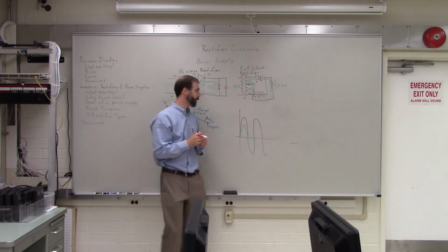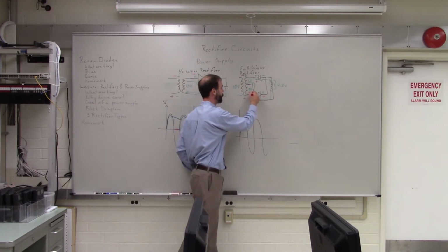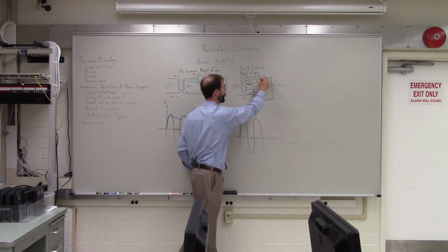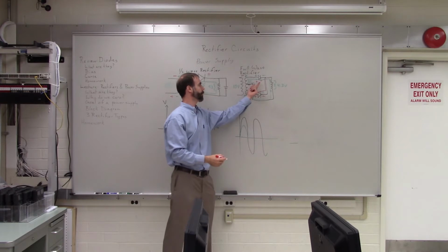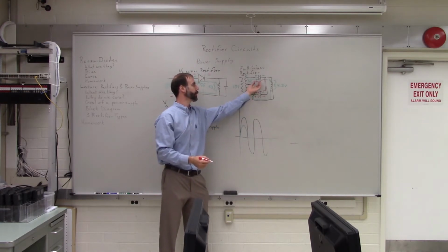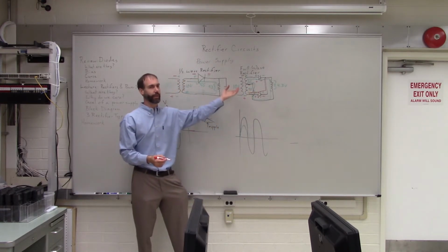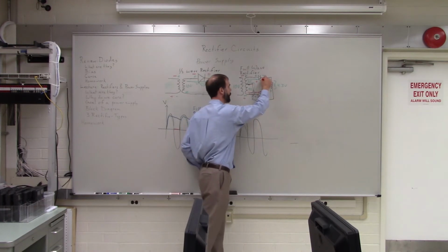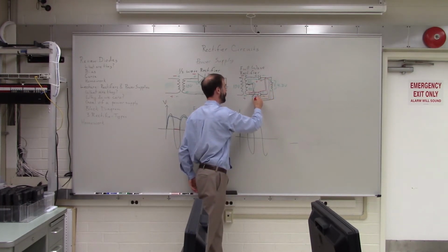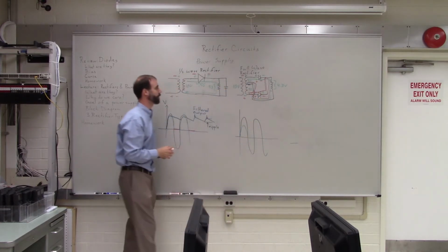Now this one is forward, exactly. So the electricity flows through there. It comes up here, it gets to this point. It tries to go left through this diode, but this one is reverse biased now. So it can't go that way. So it all has to go down through the load again. And then back up and around to the center.